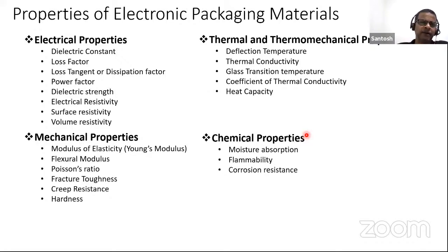So, for example, underfill material will have a different set of properties than epoxy mold compounds. Epoxy mold compounds will have a different set of properties than a thermal adhesive. And thermal adhesive will have a different set of properties than, for example, photoresists. So different materials, depending on application and end use, will need to be tailor-made into a specific set of properties to be applicable for the end application.